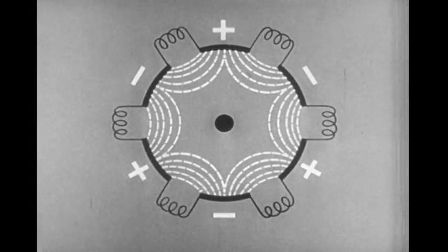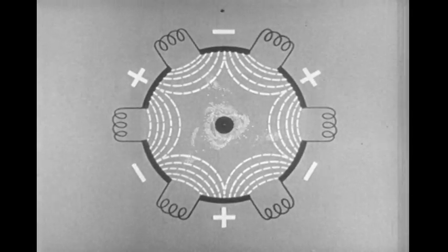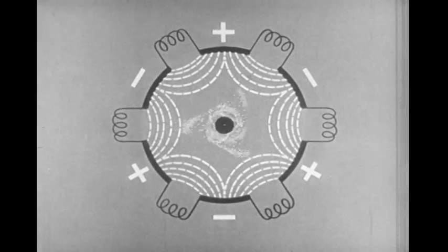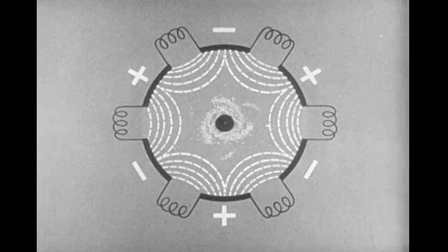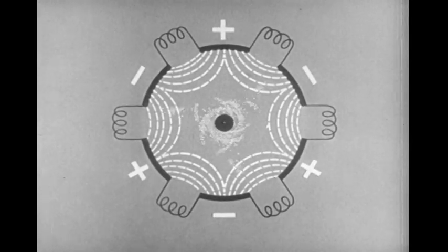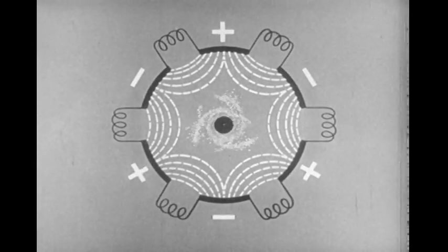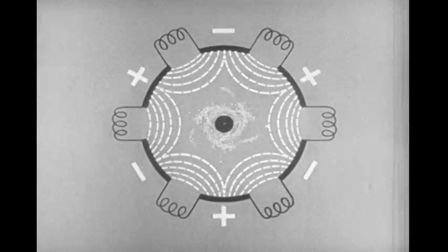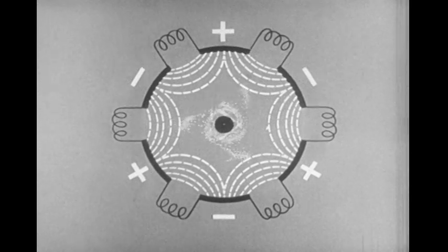In actual practice, large numbers of electrons will leave the cathode at the same instant. Those entering the RF field out of phase, of course, will be returned immediately to the cathode. But those entering in phase will follow the usual orbits until they strike the anode. Thus, there will be bunches or clouds of electrons in the in-phase region and very few in the out-of-phase region.